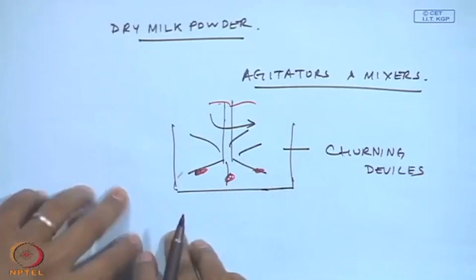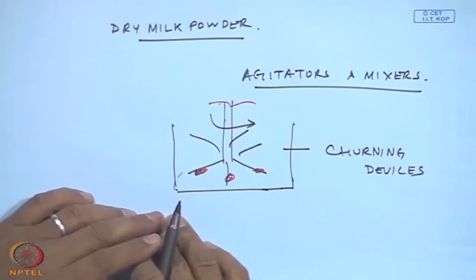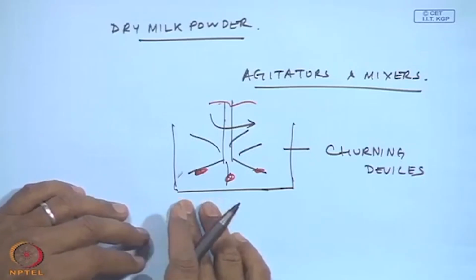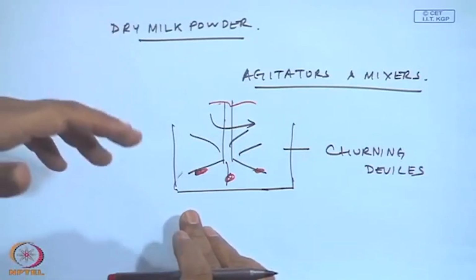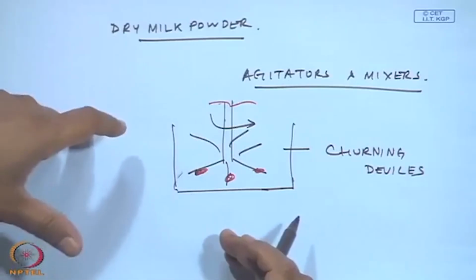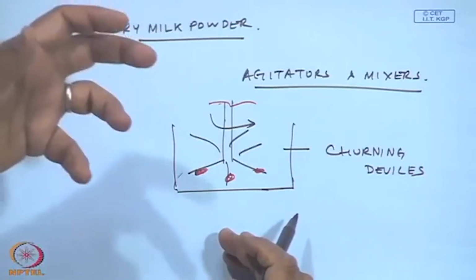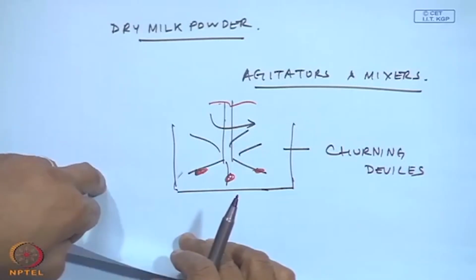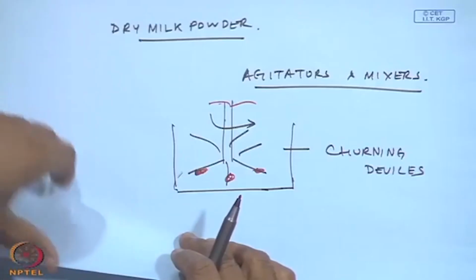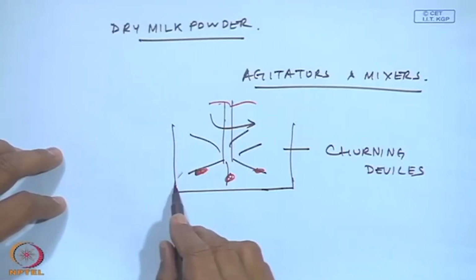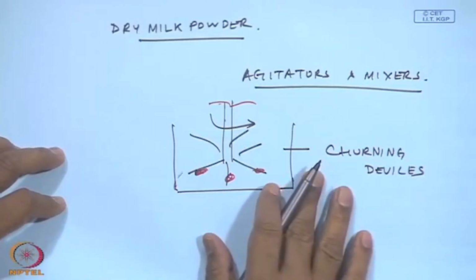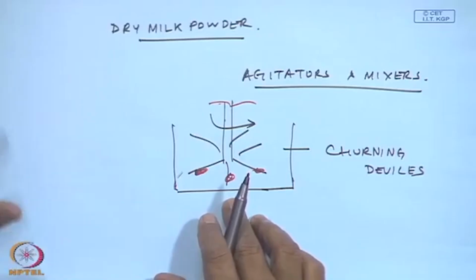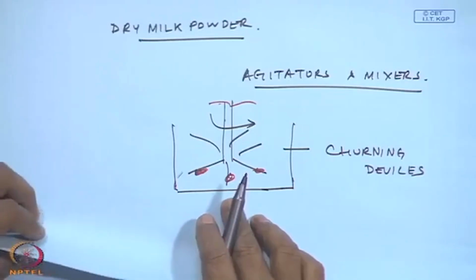So periodically in many of these plants, be it the FD fan in a power plant or an agitator in a food processing plant, in regular maintenance they scrape off the deposits, and there are alarm levels also. If they suddenly see that the weight increases, they know that something is getting deposited. You are talking about an iron ore sintering plant, a lot of things happen. A lot of places where things can get stuck will create an unbalance and then things will break off. So, the sources of unbalance are manufacturing defects, installation issues, maintenance issues and so on.